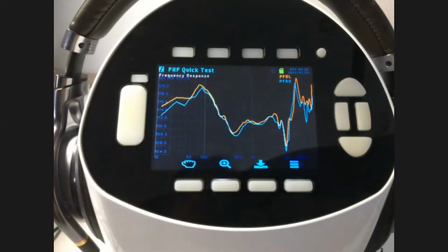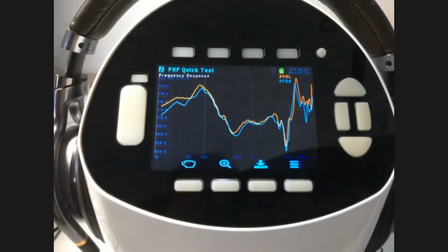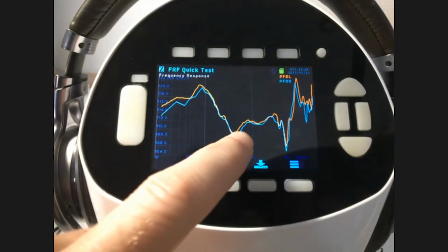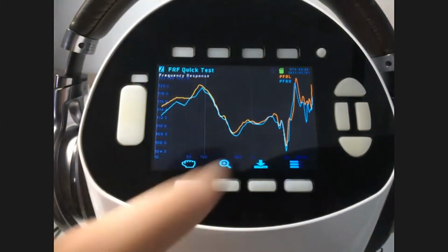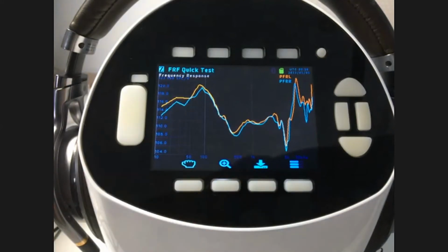If you were to put a microphone inside a speaker box with a bass reflex port, you'd see where the bass reflex port is working. It's pulling the energy off the driver and pumping it out to the back of the headphone. So the driver gets kind of stalled by that port, and therefore it has less output at that tuning frequency.